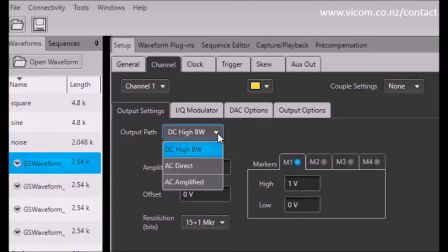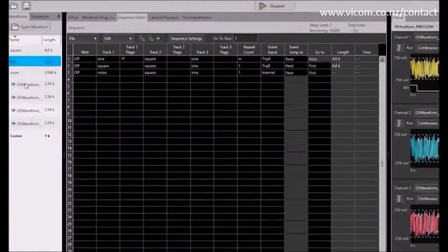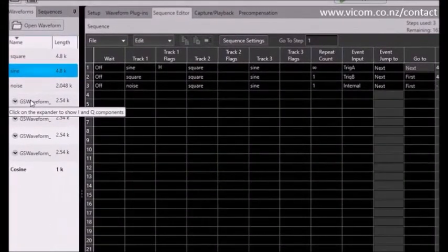for specific user requirements. Tektronix AWGs not only make use of state-of-the-art DAC technology, they also incorporate enhanced FPGA capability that enables complex sequencer and trigger modes that allow the user to build up very complex scenarios of multiple waveforms that can be repeated or jumped from one waveform to another depending on the output signal requirements.